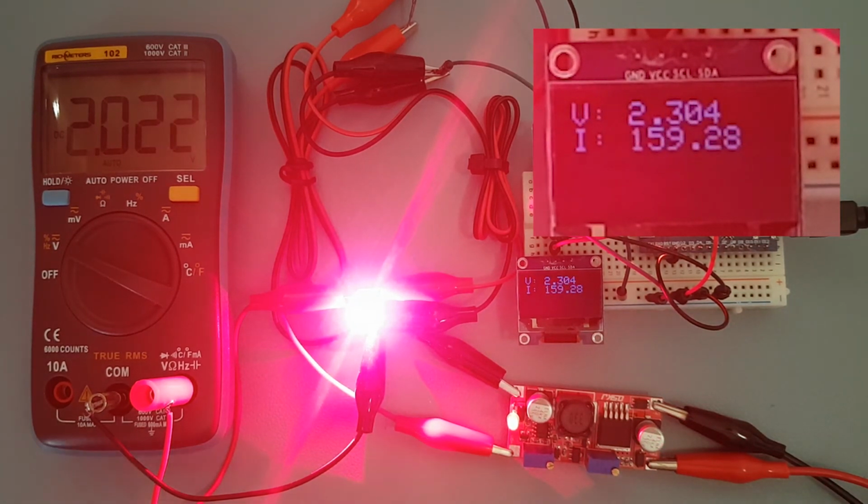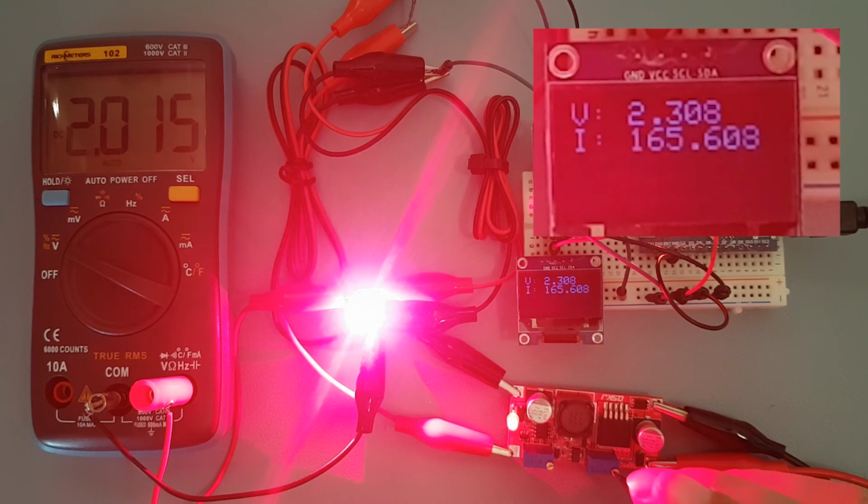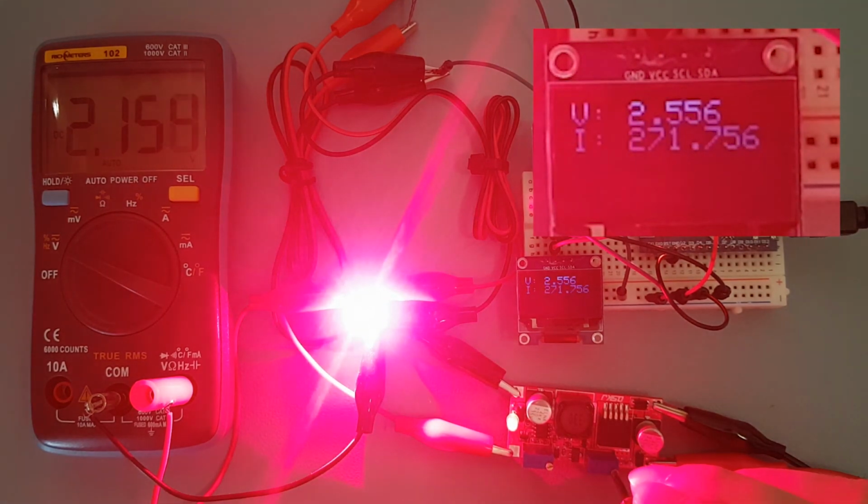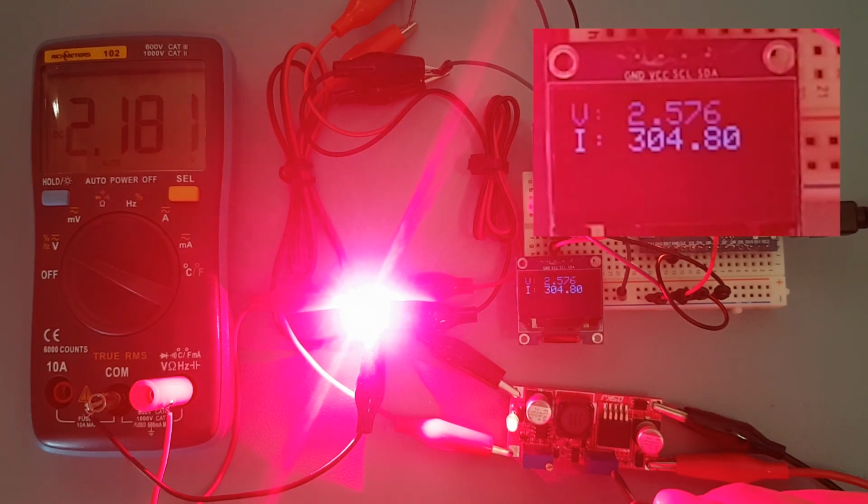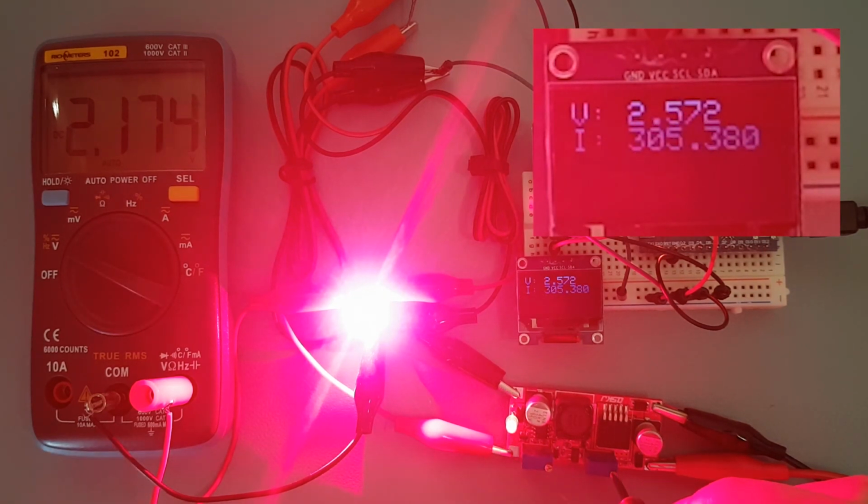The relationship between the voltage and current of the LED is characterized by the IV characteristic. As the forward voltage increases, the amount of current increases as well. Then, let's increase the forward voltage to see the CC function of the LM2596. As the voltage increases, the current increases and then saturates at 304 mA, maintaining the voltage and current at 2.172 volts and 304 mA respectively. In this state, the voltage and current will not increase even if the voltage potentiometer knob is further turned clockwise.